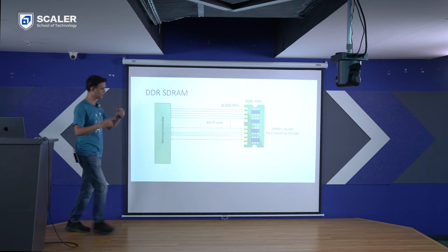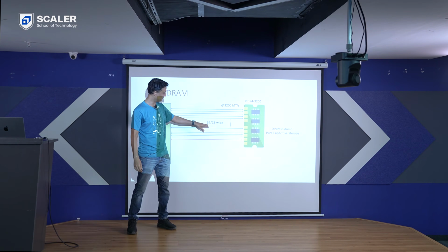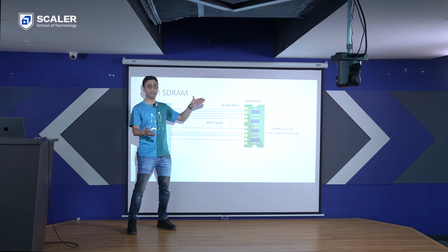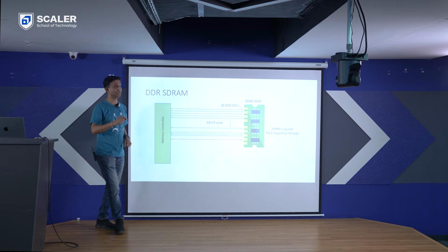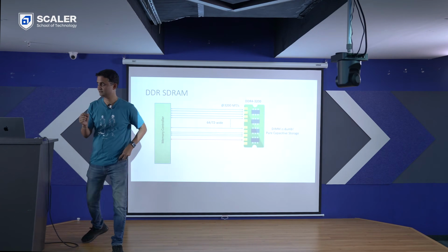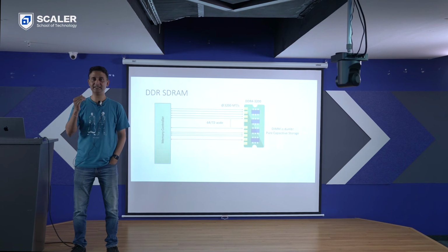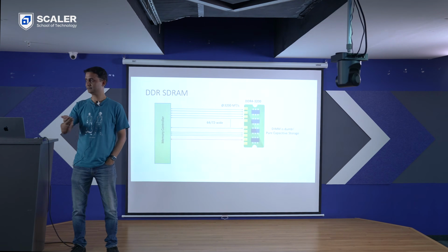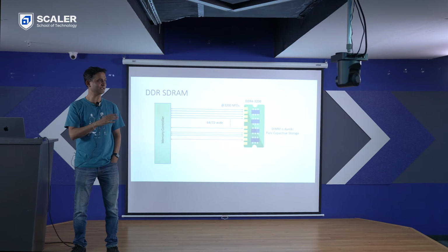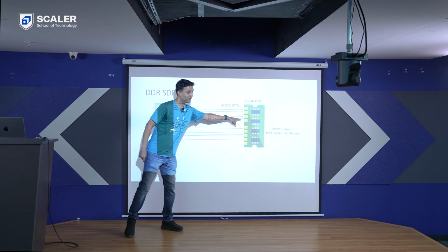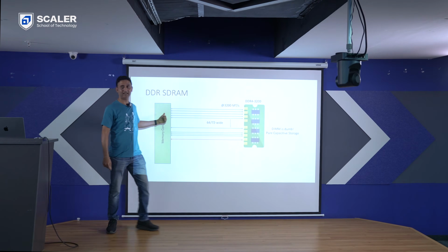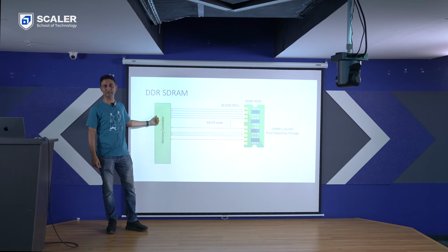How 70? Good question. Yeah, I was hoping somebody would ask that. 64 is the baseline, okay? That many number of data bits we actually do transfer. 72 is if there is ECC. ECC is error correction, okay? If there is ECC in the memory module, additional 8 bits of data end up being transferred, okay? So it really depends upon if your DIMM supports ECC and if your CPU supports ECC.